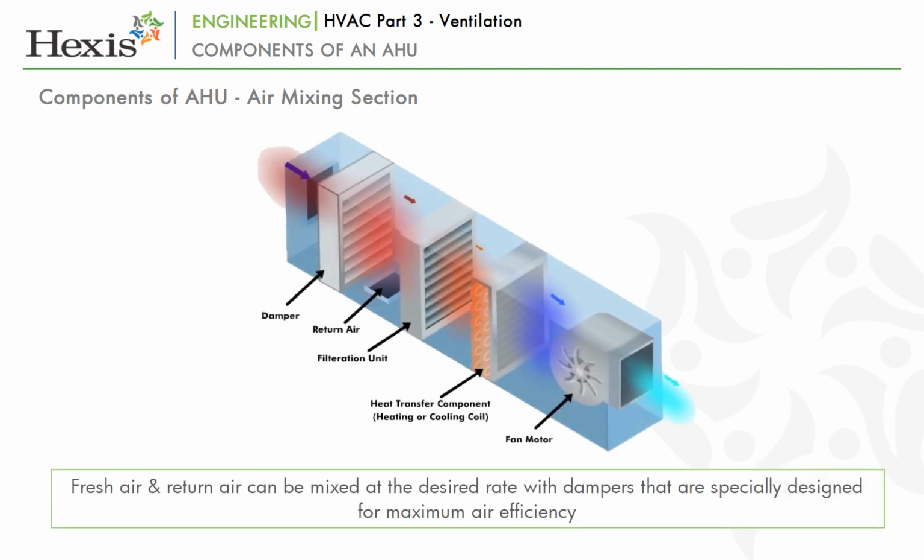Fresh air and return air can be mixed at the desired rate with dampers that are specially designed for maximum air efficiency. Motorized or manual damper in extruded aluminium aerofoil design or GSS or SS construction is available. A combination of two-way or three-way mixing chamber is also available.